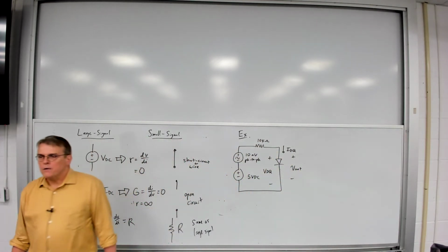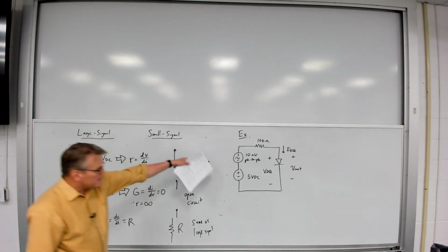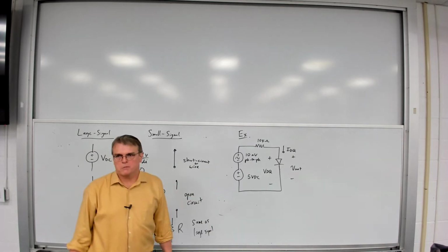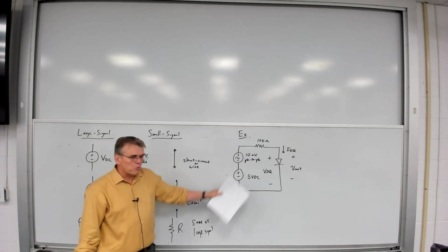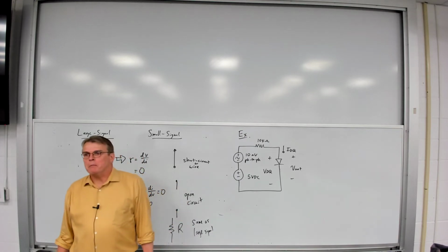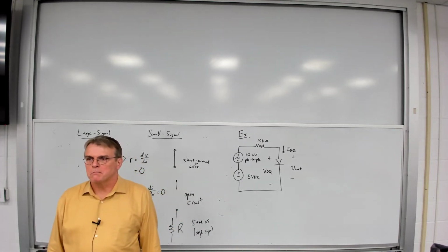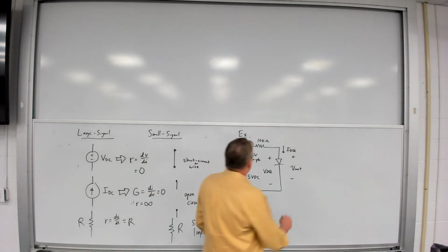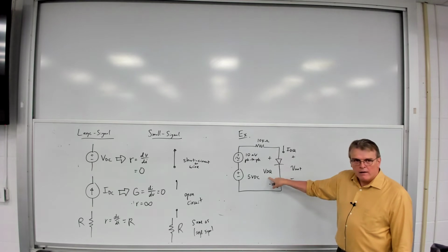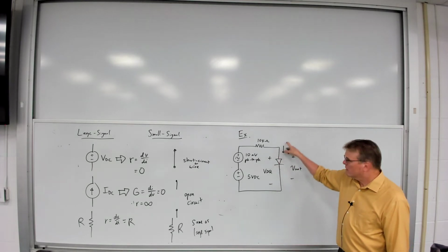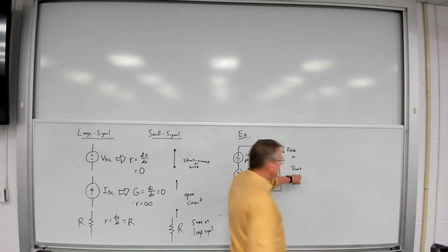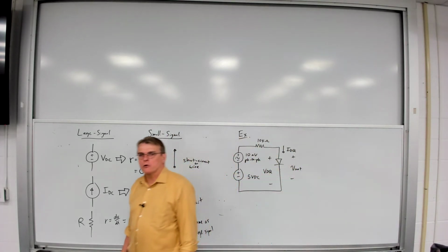All right, here is a circuit that has both a DC source applied to it and an AC source. The DC source is 5 volts. The AC source is a 10 millivolt peak-to-peak AC source. Given the quiescent voltage and current of that diode, I want to calculate and find out what will be the AC value of the voltage across that diode.